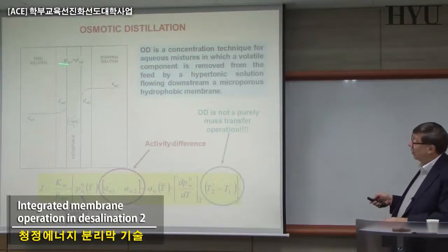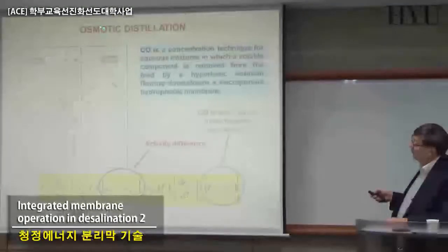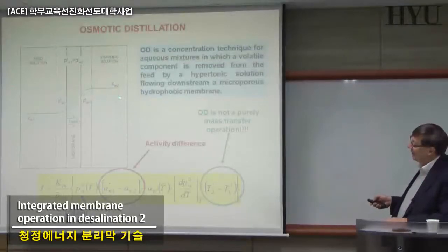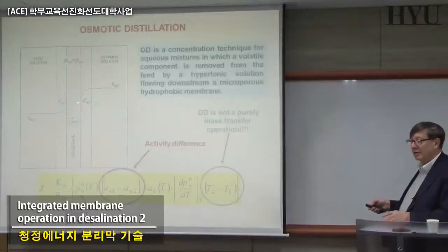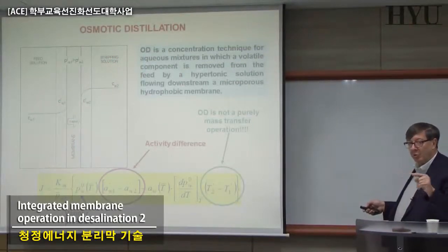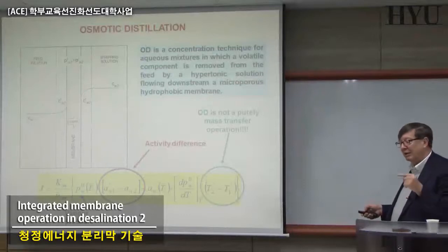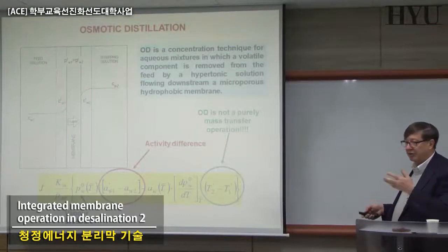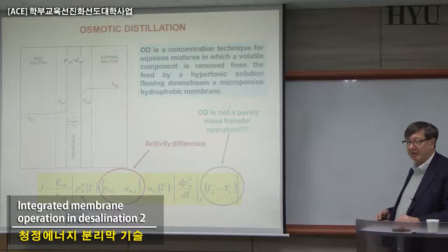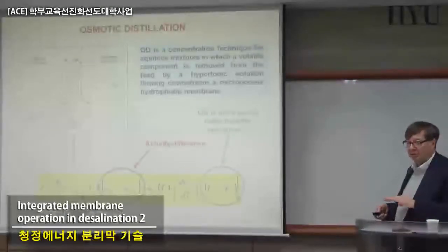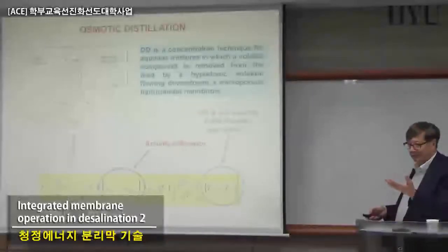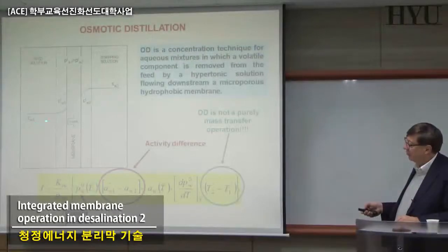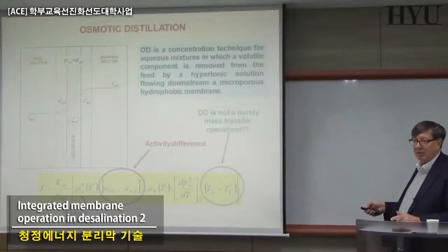In some cases, you are only using osmotic distillation, and one of the motivations for using just no delta T here and using a stripping solution down here is that if you have not only water but some other volatile aroma, when you concentrate some perfume, etc., you don't want to destroy the bouquet, the flavor, by losing not only water but also some aroma.